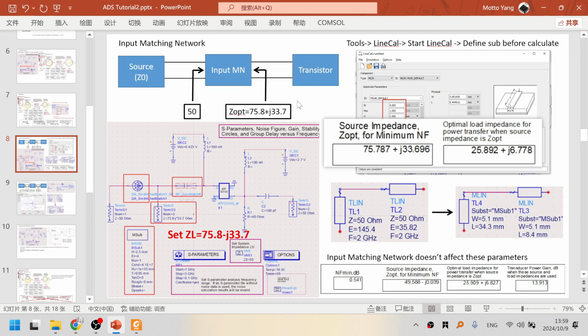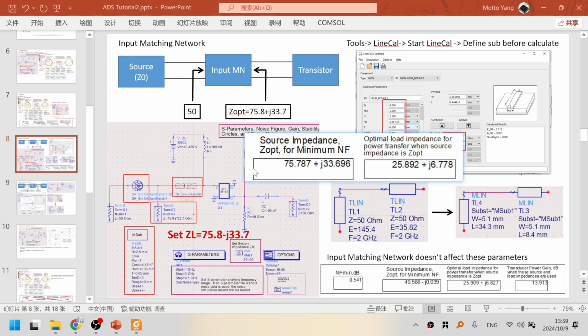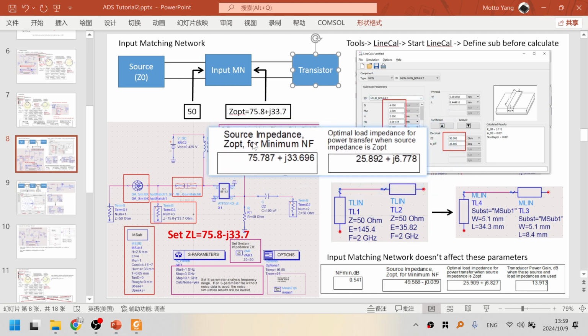But it also means that if we look at the same kind of impedance with a conjugate matching, under that case, we'll have a maximum power delivery of conjugate matching. And if we look at the impedance from the network into the transistor, we would have a minus J value instead of a positive J, because we're designing a conjugate matching.